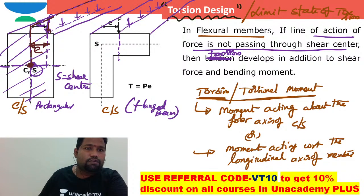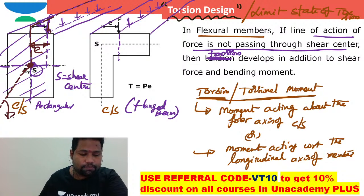So because of which, about this axis, what is this axis called? About the polar axis of the cross section, there is a moment, which is P. If this reaction also passes through the shear center, and if I take this P force effect here, two equal and opposite forces P into eccentricity e, then definitely on this cross section a moment has developed about this polar axis.